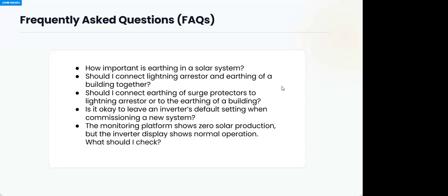Well, you are seeing no current and it's showing load. I think you are referring to an external charge controller, right? If it is an external charge controller, the way they are designed, some of them have a section where you can connect a load, and that load may be USB compatible and may just be a bulb that is controlled in the evening.